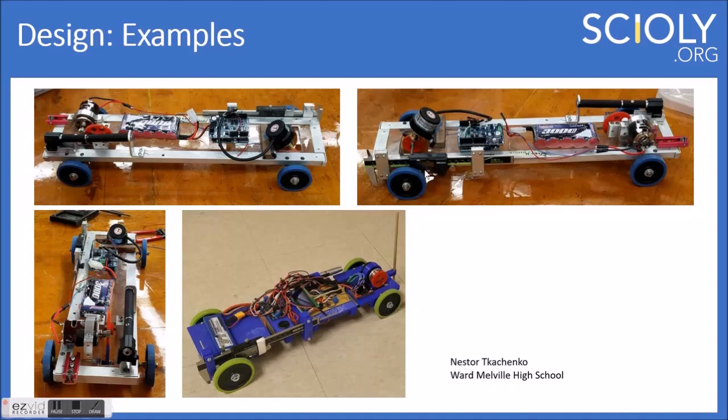He attached the caliper to the axle using this kind of pillow block, and from there he relied on the play inside of the bearing to be able to adjust it. So moving that caliper adjusted the angle that the axle was at, and that resulted in different changes in the steering.